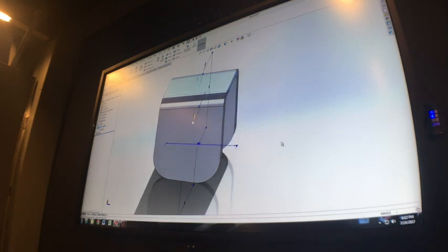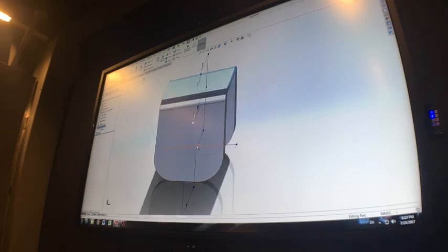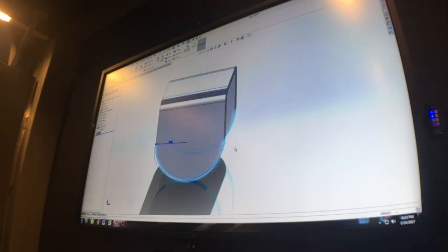You change that 40, but now you no longer have that semicircle on the bottom. If your design intent is to have that semicircle, maybe the fillet tool is not the best solution, because as well as changing that dimension from 25 to 40, I have to change the fillet dimension from 12.5 to 20 to maintain that semicircle. Does that make sense to people?